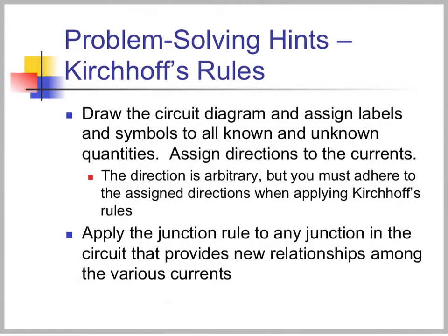Now, we might not know the direction just looking at the circuit. Sometimes we will. That's okay. We choose a direction, and it might be arbitrary. But if you follow all of the Kirchhoff's rules carefully, at the end, if you solve for a current and you get a negative value for it, you knew you chose the direction in the wrong direction, it'll come out in the end. You'll know the magnitude and direction in the end, whether the current is positive or negative.